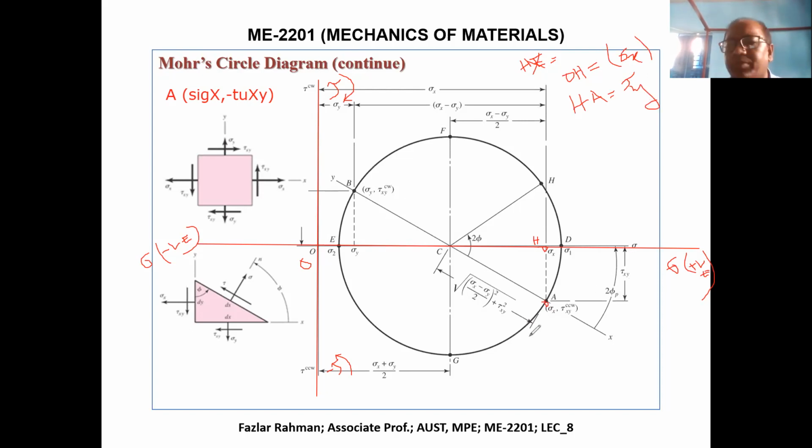Okay, now I look for this point. This is my B point. So what is the B point? At point B, my sigma y, normal stress. So I put sigma y, comma. Look at the shear stress. It is rotating clockwise, so it's positive. So tau xy. Now this point I'll put in the graph paper. And right over here, we are thinking these are all numbers. I'm sorry, there's no number, right?